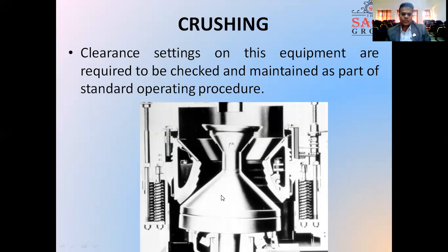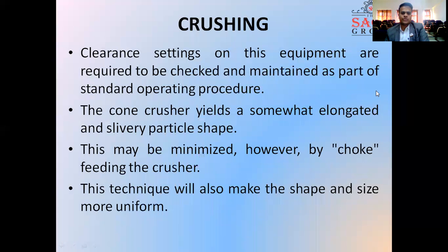In between, the cone is oscillating up and down so that the material enters and is fitted in between, and due to the oscillating motion of the cone, the material, or the aggregate or the particles, are broken into smaller pieces. The clearance setting on this equipment is required to be checked for maintenance as part of standard operating procedures.